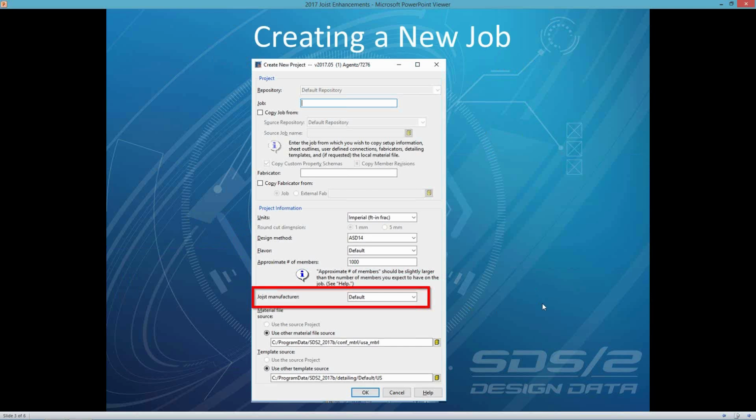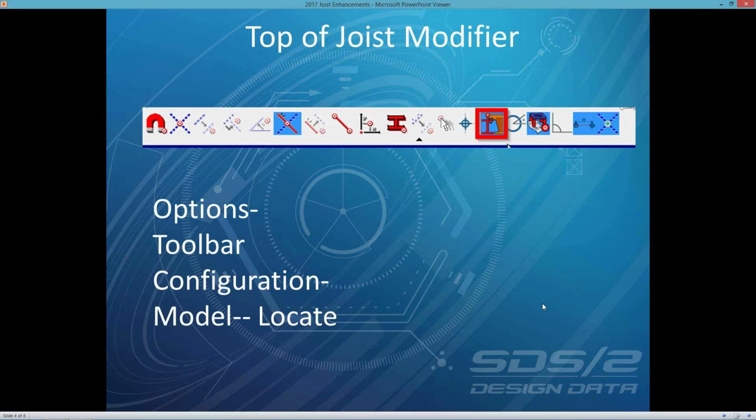The top of joist elevations are set from within the member edit screen or using the top of joist location modifier. So there are two ways that you can add this in. By default, it'll add it at the bearing elevation or where there's a connection to the supporting member. Or you can use this modifier. It's located by your point locates. It will say to put the joist at the top of the joist elevation. Then you will need to use your point locate still with the modifier.